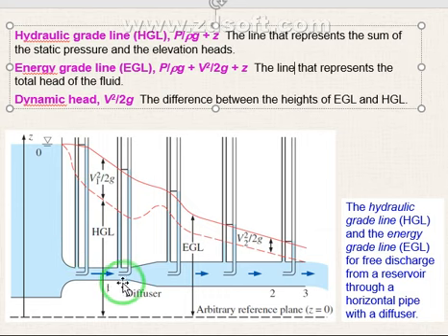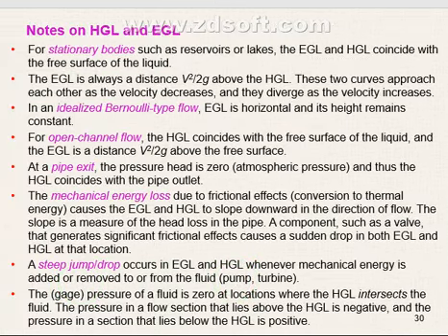Here the difference in the small radius pipe is bigger than the difference in the big radius pipe because the velocity is smaller here. But in general, you see there is a drop, meaning that we have losses here. That's why the total energy is dropping or declining with the distance, because we have friction losses. We have other losses too.